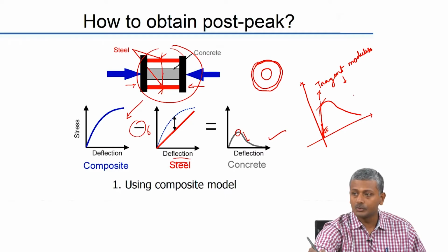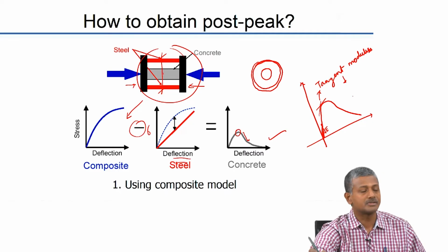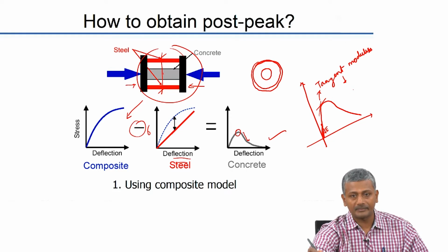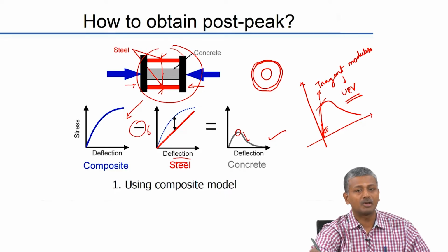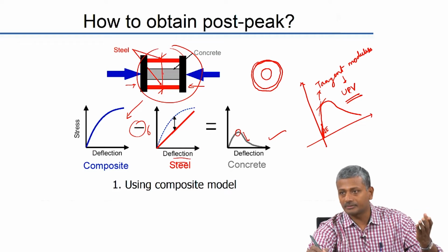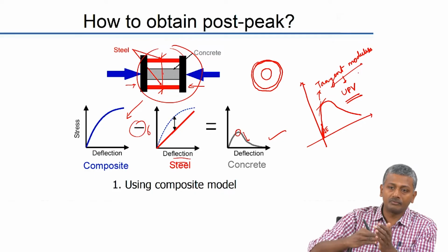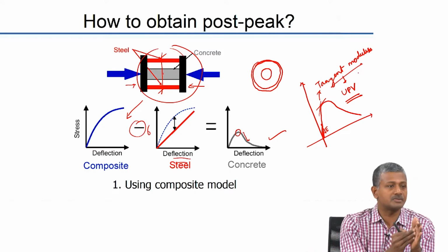So, you can actually use this tangent modulus and measure the properties of your cementitious composites by non-destructive methods like ultrasonic pulse velocity, okay, and convert the velocity into the modulus in a manner similar to tangent modulus, that the velocity will also be very high when the system is undamaged.